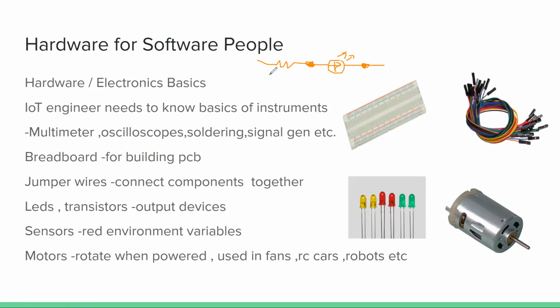So we use wires. Here maybe you have the Pico, or the Raspberry Pi, or the Arduino, and then you connect it through a resistor, then to an LED, and then you connect it back to the ground. We did that, isn't it? The jumper wires are just wires made out of copper.